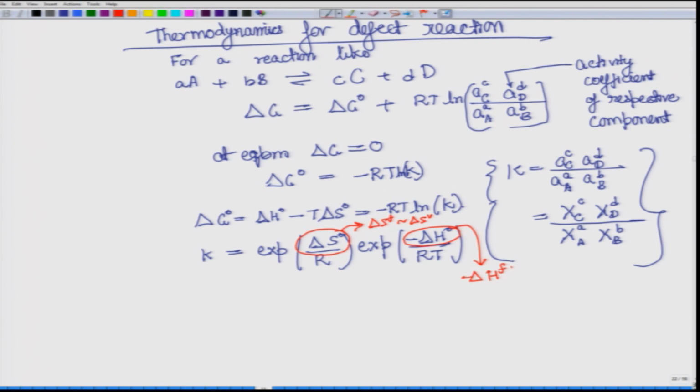So whether it is about one vacancy, one Frenkel pair or one Schottky pair, it can also relate to those formation energies. In this particular case, it is talking about the change in enthalpy when this reaction goes from here to here. Now, this is an equation very similar to what we had obtained earlier. So here we can now write it like this.